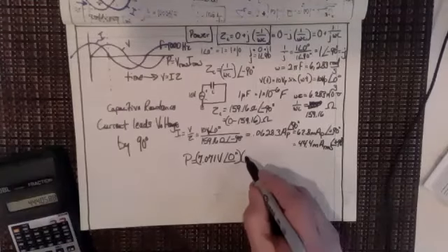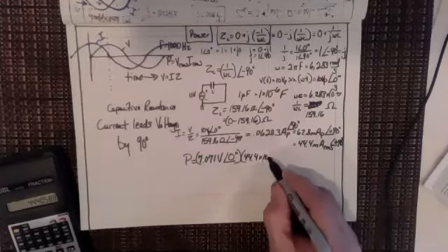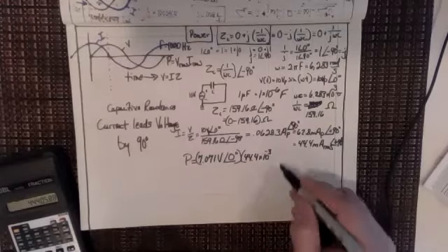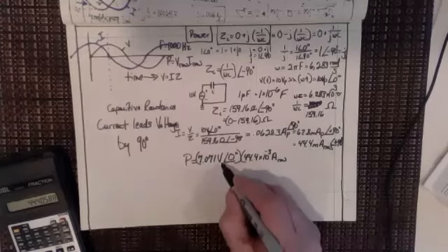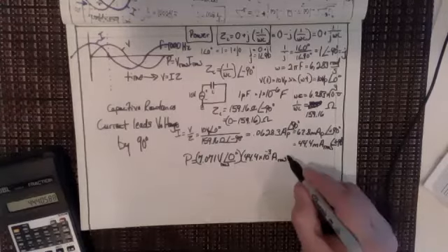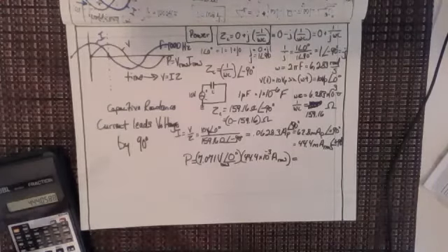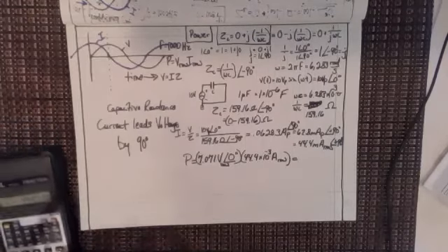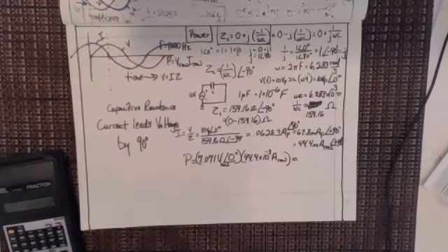And of course, it's still at the same angle, 90 degrees. So I've got 44.4, and now, you know, I might as well say times 10 to the minus 3, because that's how I put it into my calculator, A RMS. That's volts RMS, of course. I want to always emphasize that this is always RMS that we're working with for power calculations in AC network theory.